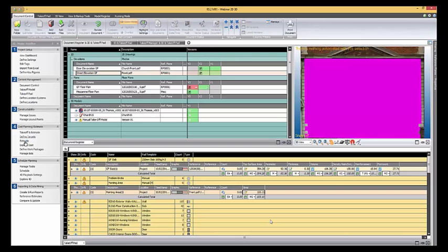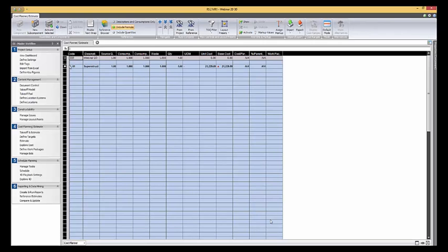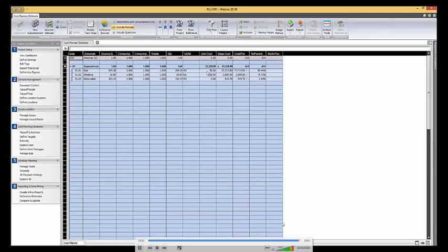Okay, so all I have to do now is zip back to my cost plan, break that open, and you can see that 18,858, I believe, has gone up to 21,229. I can run reports to export in PDF or Excel to isolate where we had price changes due to these changes in either the model or my manual takeoff. So I can get to the bottom of where those changes came from, and I can also issue them in PDF format to my client or to my subcontractors if I've already divided it up into subcontract packages.